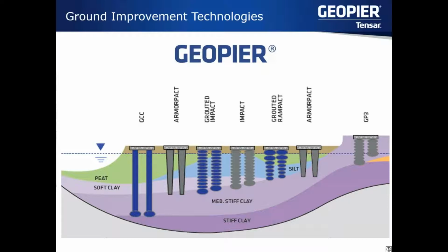These elements install very well in clay soils, soils where we don't have too many concerns about the water table. But when we look beyond the narrow scope of those specific soil conditions, we can see that there is a lot still that needs to be addressed. As we've expanded our operational capabilities, we're addressing many soil conditions beyond that. We're addressing peats, organic material, soft clays, and we're also installing these elements in high water tables as well.